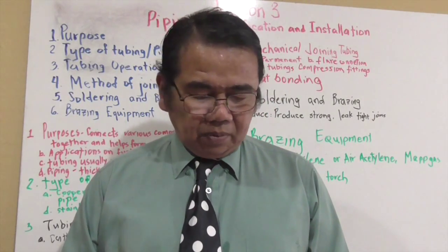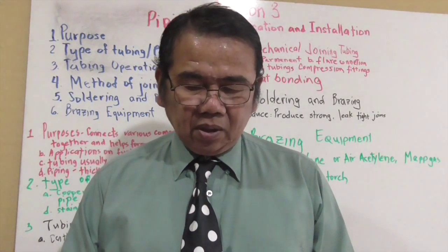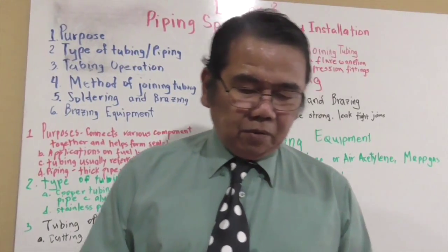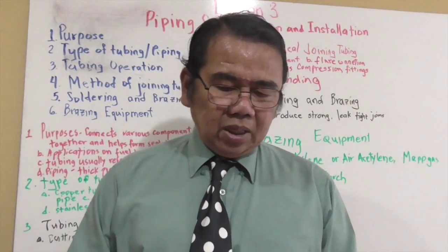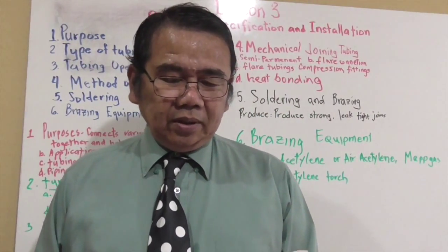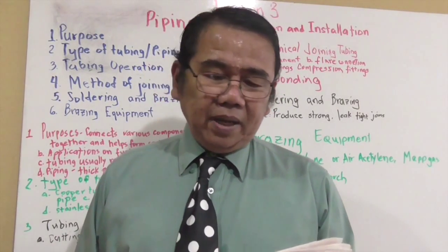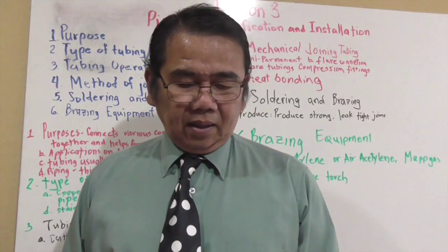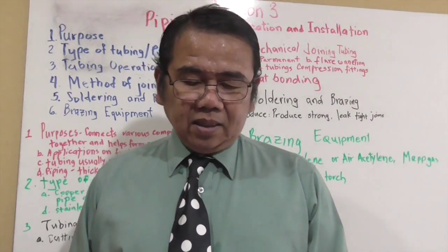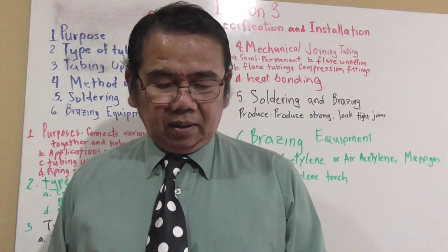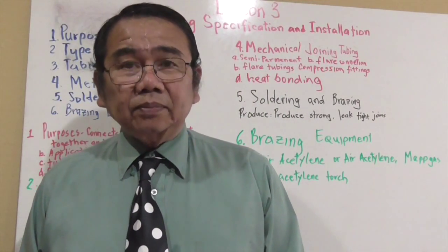And then the next one we talk about is the four steps of preparation. We're going to first do proper fluxing. Flux does not clean the metal. It keeps the metal clean. Available in both paste or liquid form. Paste is the most popular. Select the proper flux for the job.